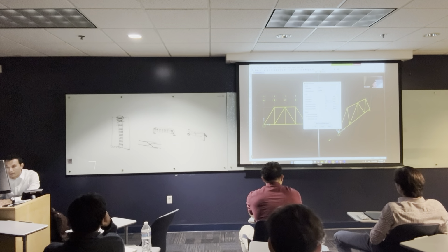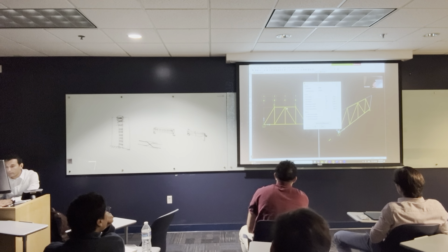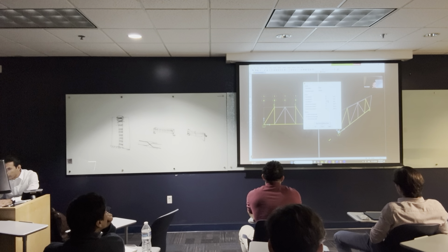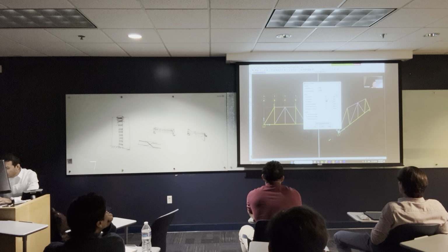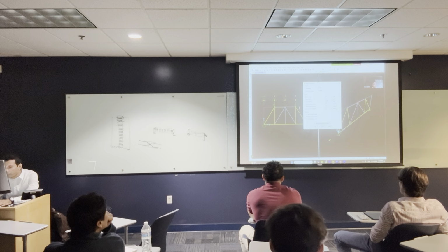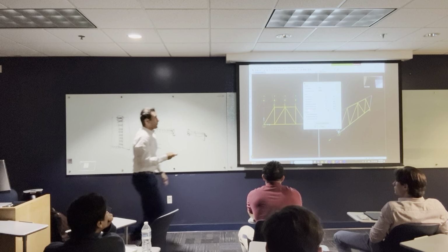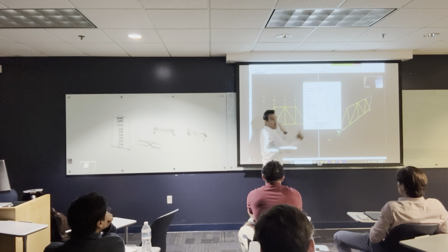I always have replace existing loads, just in case. And then I'm going to say apply. When I apply, the load is going to show up here, 4.2. Then I'm going to select this joint, and I'm going to come here and assign a different value of the load, which is 5.5. So I'm going to say negative 5.5, and I'm going to hit apply. All right, so we put all the dead loads here. I keep this open, and I keep selecting and assigning until I finish them.